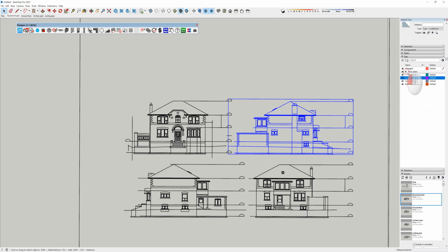So you'll notice that we have a floor plans folder that I created there first. What I probably should have done is put all of my floor plans inside of that folder. I can drag and drop them up. You'll notice that I still haven't got my first floor in there. Drag that inside of there as well. I need to turn it on. Okay, so now I have all of my floor plans inside of a folder,